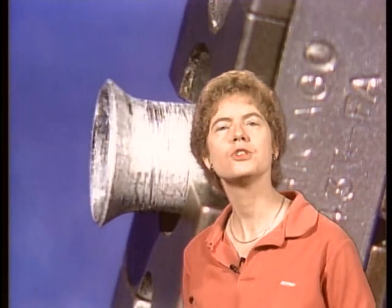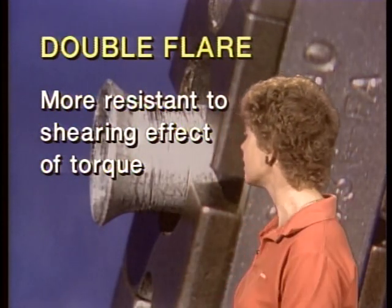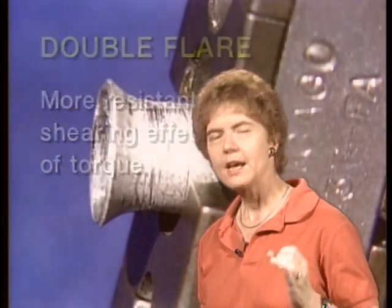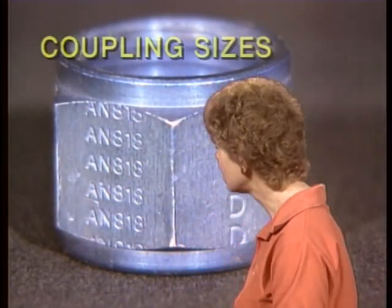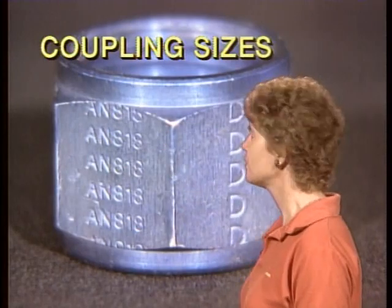Now, sometimes you will make, instead of a single flare like this, a double flare. And the advantage of a double flare is it's more resistant to the shearing effect of torque. Now, couplings come in various sizes. And how do you tell the coupling sizes? Well, the FAA says that there's going to be a dash and a number after the end of the coupling.